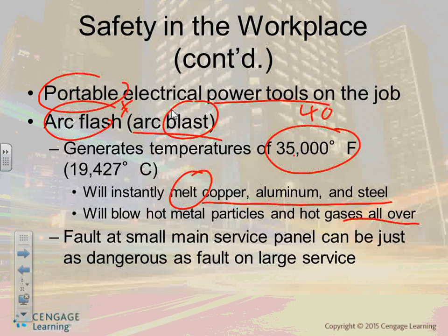Technically, you should put on your PPE when you approach that boundary. They call it the arc flash boundary. When you get into the arc flash boundary, you have to put on your PPE. It's not enforced a lot on the engineers, and it's not practiced a lot. Or give the electrician, while he's putting on his PPE, the camera to take a couple of pictures from the inside of the switchgear, if you're not putting it on.